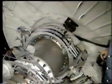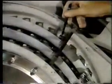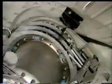Start the engine, and while the speed is below 66%, check the position of the vane. The scale should read -35 degrees or C on the inlet scale, -29 degrees on the first stage stator scale, and -24 degrees on the second stage stator scale. If there is a deviation in the specifications, check the position of the tool over the center hole of the inlet guide vane pivot shaft. If the tool's alignment is correct, the vanes must be adjusted.